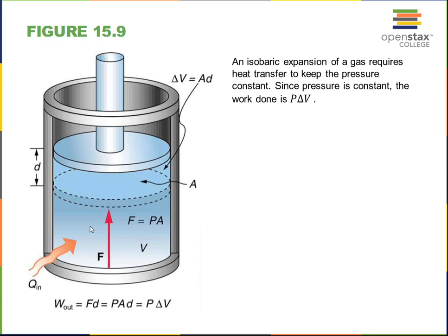We put in more energy, and that will increase the energy in our system. The molecules travel faster and bounce off with more force from the bottom of the piston. So our force is pressure times area. We're going to have the ability to lift this piston with enough force being present as we put in more energy. Work is force times distance. Work can be calculated as pressure times area times distance. And this area times the D gives us a new volume, an increase in the volume.